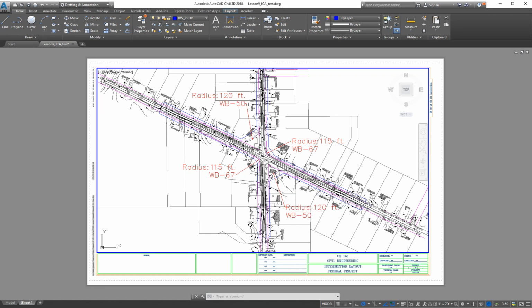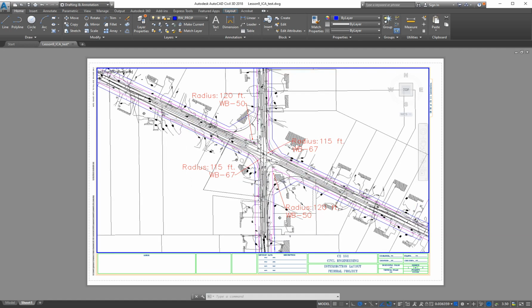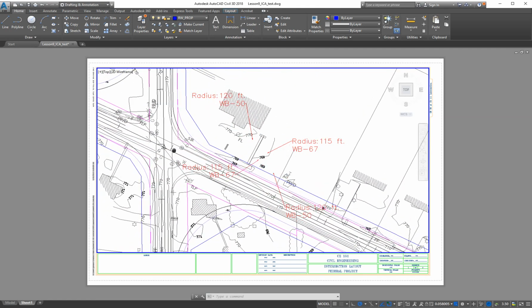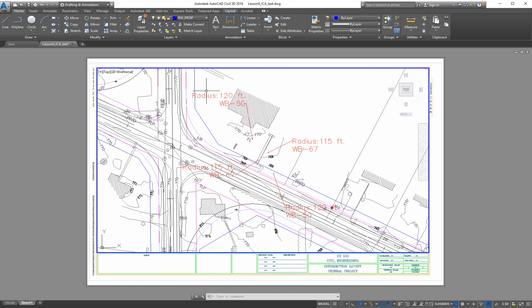And I can touch stuff now, right? If I'm hovering over these line pieces or the line work from that drawing, I can interact with it, because I've actually gone outside through the window and I can still see where the frame is. What we do with this is we can change that scale. I can make this much bigger. I can move things around if I wanted to. Notice the red text that was in paper space didn't move, because it's like it's drawn on the window. It's like you've got a dry erase marker and you just wrote on the window, right?